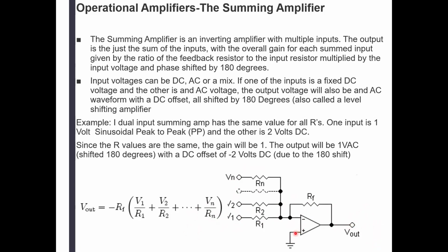But if you put that at the 5 volt level, for example, then you're going to have the same signal, but it's going to hover not around 0, but it's going to hover around 5 volts. So it's going to be whatever the AC signal riding on the DC component, which is going to be determined by whatever this thing is sitting at instead of the ground. Right?